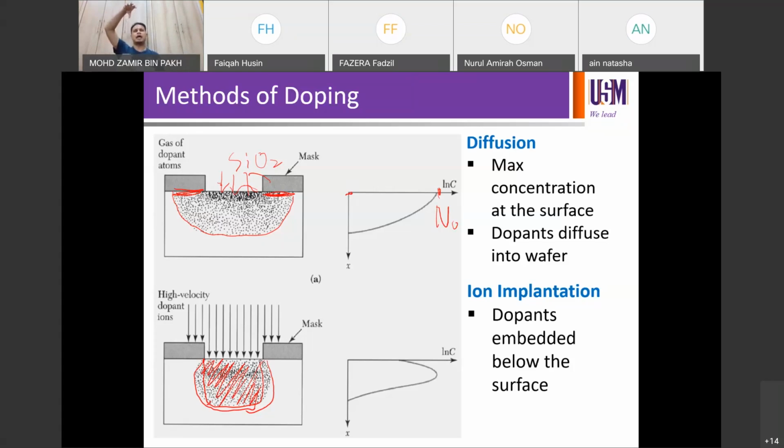You can even ion implant the dopants into the silicon without disrupting the surface. You boleh actually embed the dope region to dalam. You can do that actually by high energy. You're going to see later on that you're going to have low energy implanter, medium energy implanter, high energy implanter to do various jobs during the fabrication process.